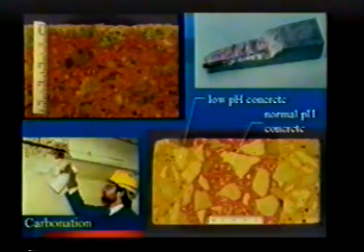If there's a bar in here, I can guarantee you you're subject to corrosion. And you can see the sample here. This is uncarbonated, here it's carbonated, and here you're having a rusting rebar. If you're in the field and you can't send it to a lab, well, you can still check. Here's the worker spraying phenolphthalein on the sample where the concrete has been removed. So we can field check if there's a carbonation issue.